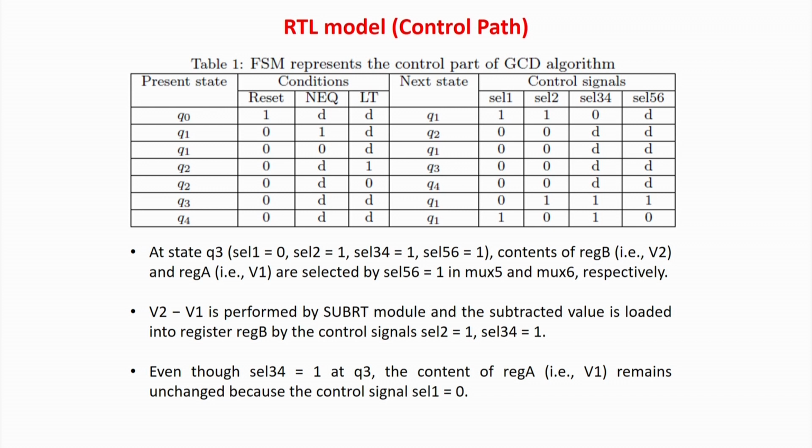There will actually be 4 states. 4 states means it will be a 2-bit machine, so the number of flip flops will be 2. Actually it is 5 states, Q0 to Q4, so the number of flip flops required will be 3 to implement the circuit. The important part is that this is very standard digital design. You can easily go back to your higher BTech level digital design, and you can easily find out how a state machine can be implemented.